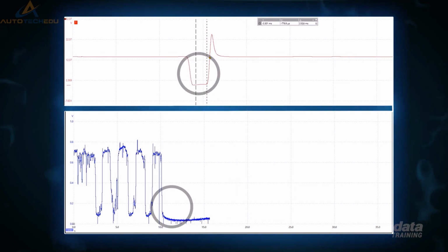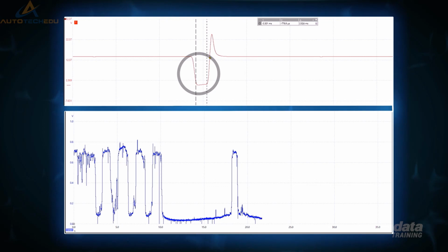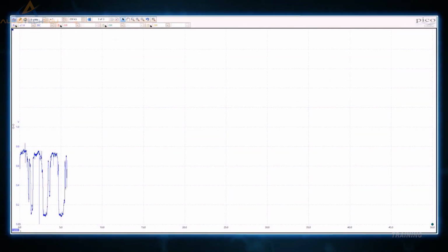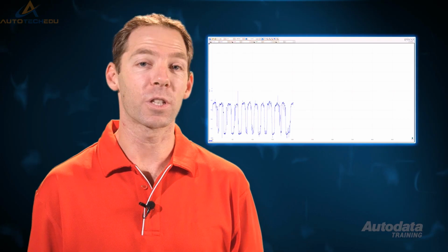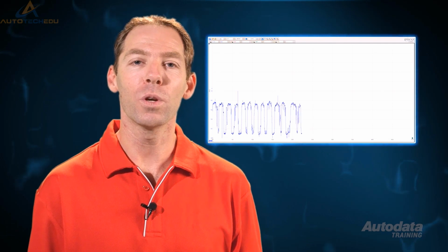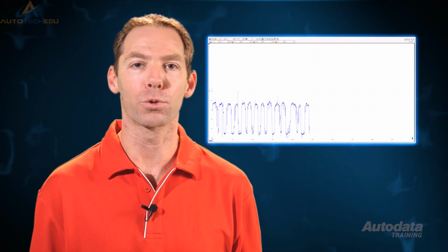You'll notice that the O2 sensor reacts to the leak a moment before the injector pulse width increases. If we keep watching the O2 sensor signal, we can see the pattern returns to normal after a few seconds. The mixture has returned to a stoichiometric value, and yet we still have the air leak. To explain how this works, we'll need to look at the vehicle's fuel trim data.